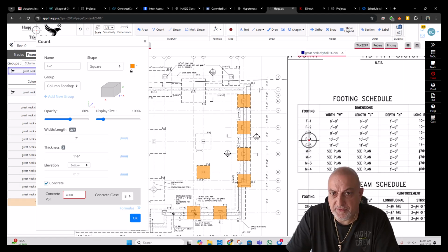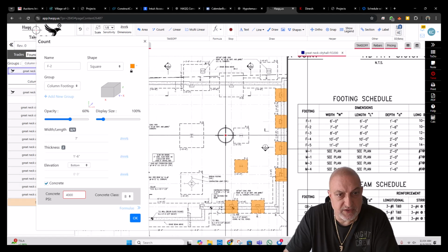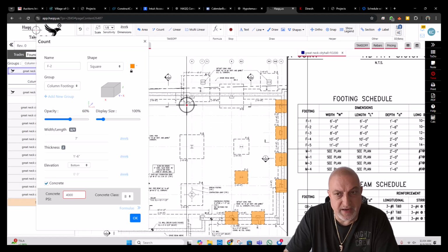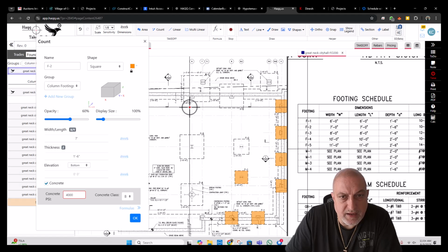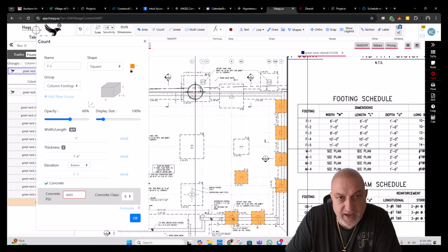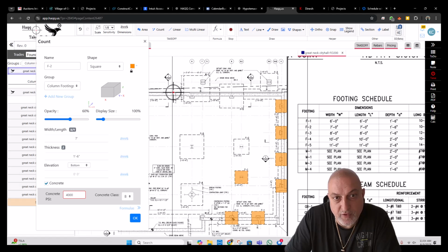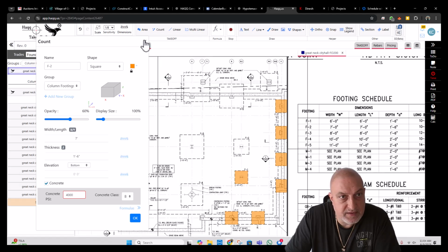See, the footing thickness on the F4 is 2 feet and F5 is 2'6". Let's take a look at this. F4, does it affect? Minus 15. Okay, they fixed it. Top of footing elevations we have to make sure are the same, so formwork for the walls sits on the level. We are not creating any step in between here.